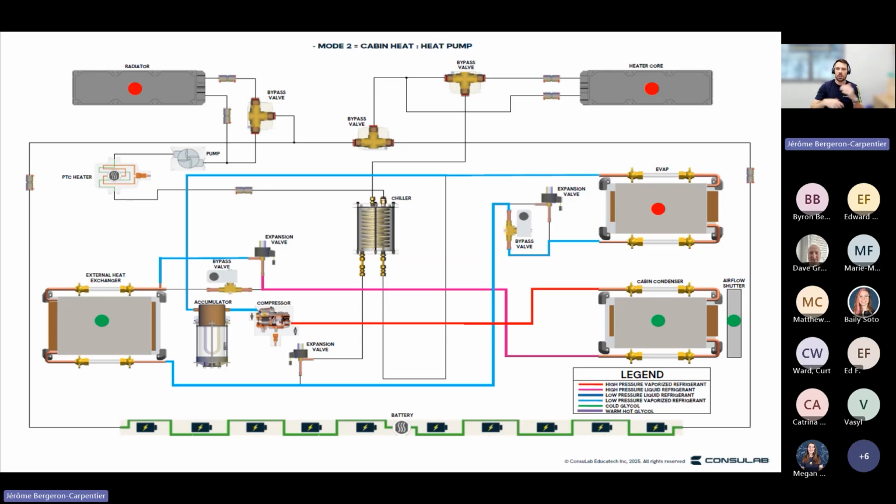We are not going to use a lot of energy, but we're still going to be able to heat up the cabin. We have the compressor compressing, but now we want the heat dumped inside the cabin. So we have the fan for that heat exchanger turned on, and the airflow shutter is also turned down. So we have the heat transfer, and the heat goes inside the cabin.